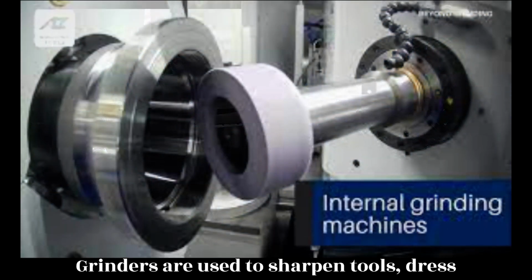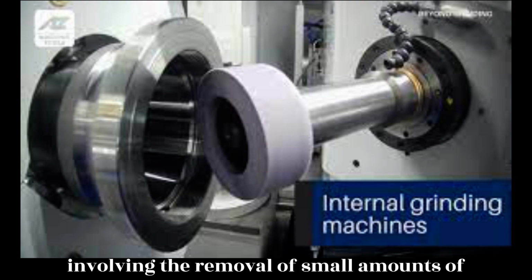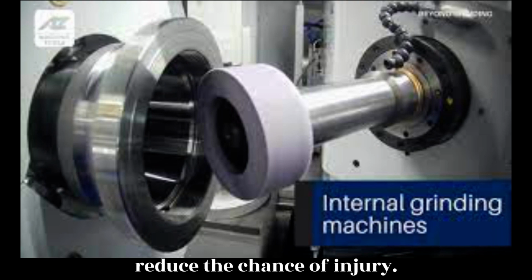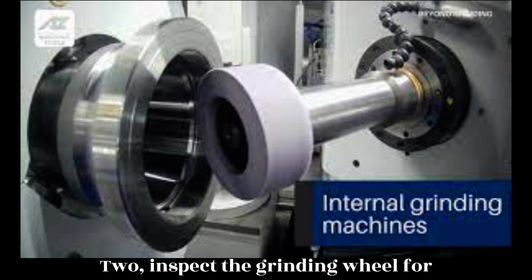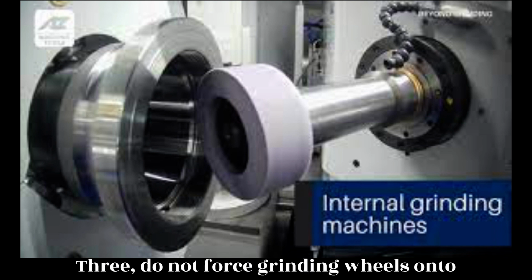Grinders are used to sharpen tools, dress metal, and perform other operations involving the removal of small amounts of metal. The following precautions can reduce the chance of injury. 1. Wear eye protection, even if the grinder has a shield. 2. Inspect the grinding wheel for defects prior to use. 3. Do not force grinding wheels onto the spindle.